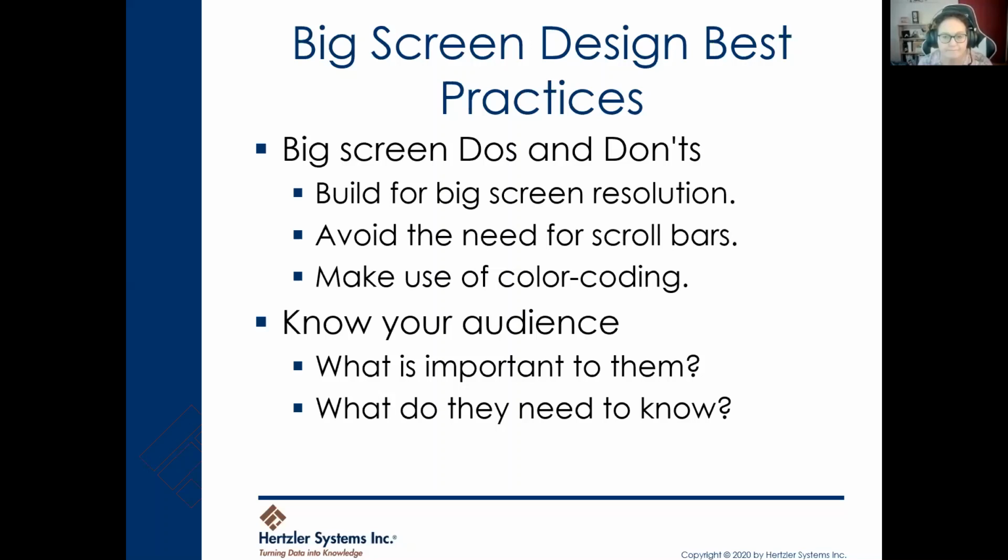If you've got that, you've got a portion of your dashboard that the operator cannot see. Another thing in big screen displays, though this is also for just looking at it on your monitor, is make use of color coding. Make things that the operators need to take notice of jump out on the screen.